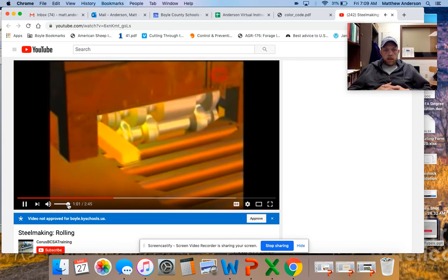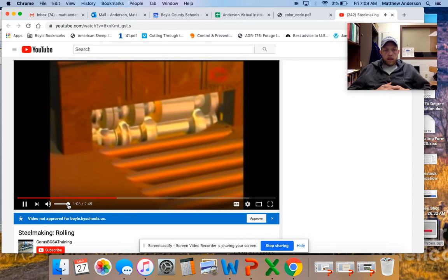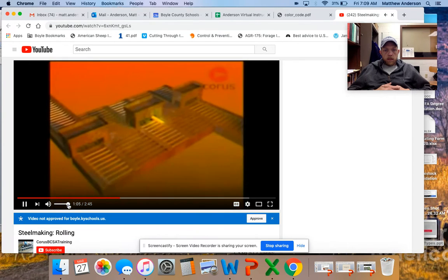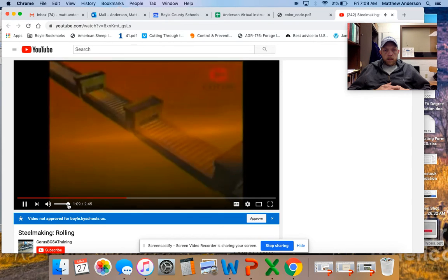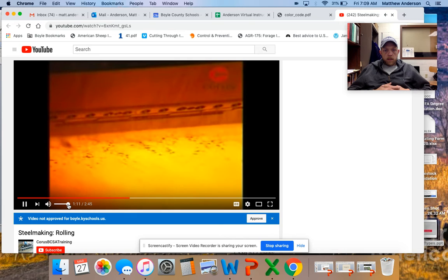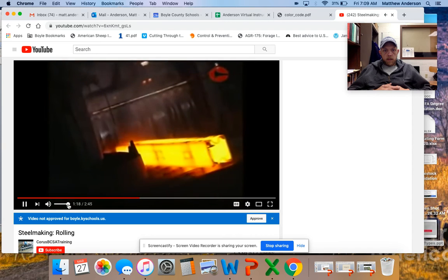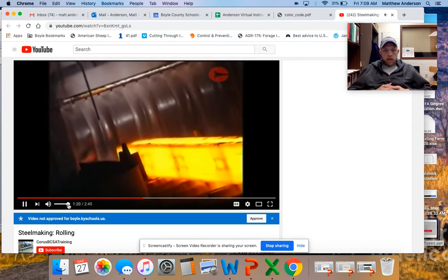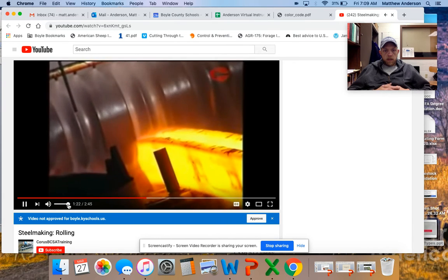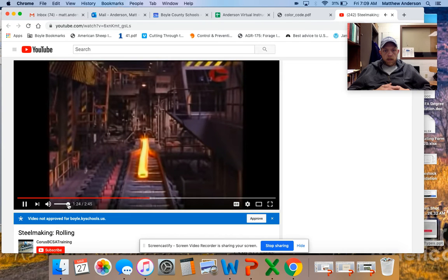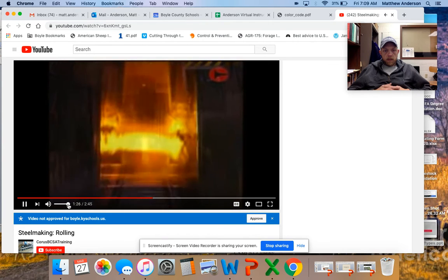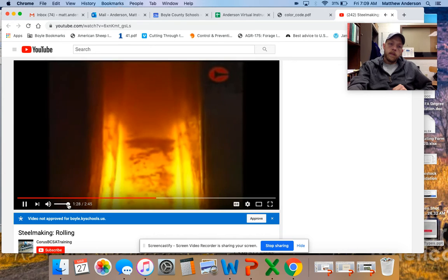The layout of a rolling mill can vary from a simple single-stand mill to several stands positioned either side by side or in a line. The mill rolls themselves can either be plain for flat products such as strip, used for products such as cladding, or profiled for sections, beams and columns for use in construction. Mill stands have various roll arrangements depending on the product being rolled.